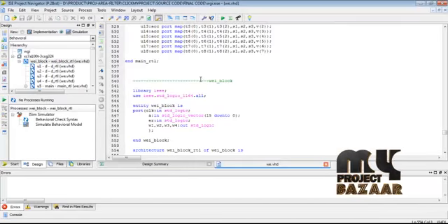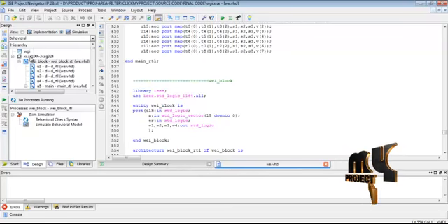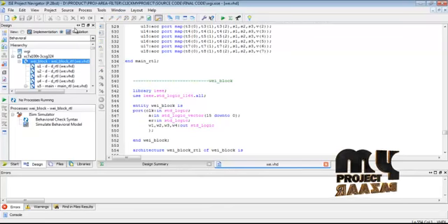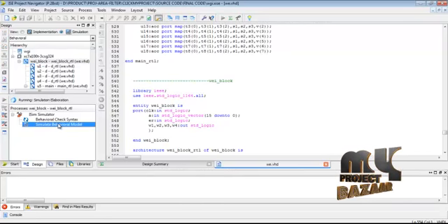Our program is developed in the VHDL language. Then we select the weighted update block to select the simulation work, then select simulate behavioral model. We run the process for our processing result, then open the Xilinx ISim project.